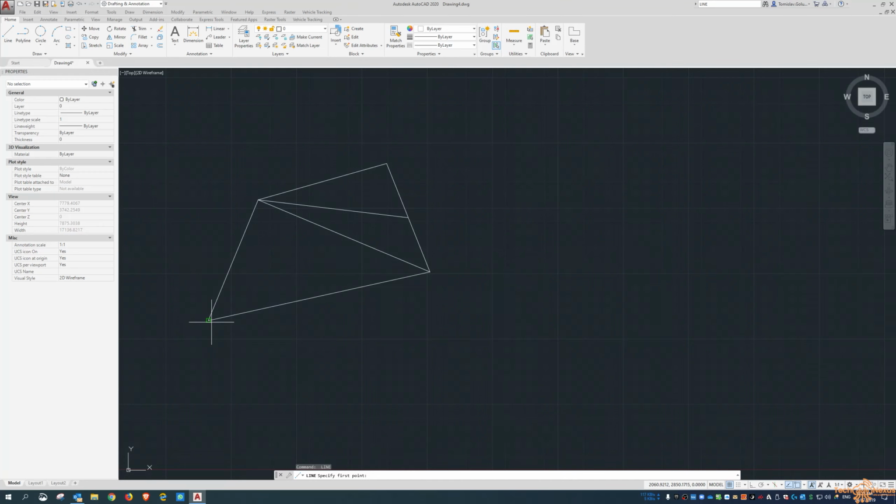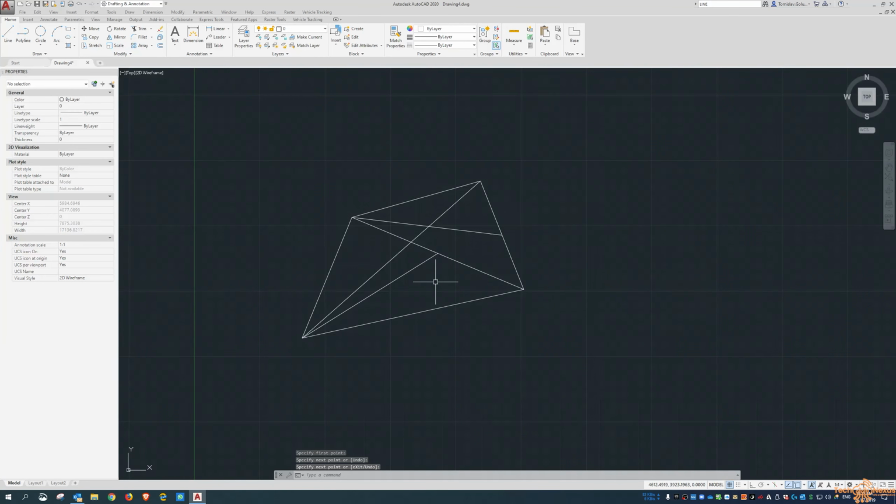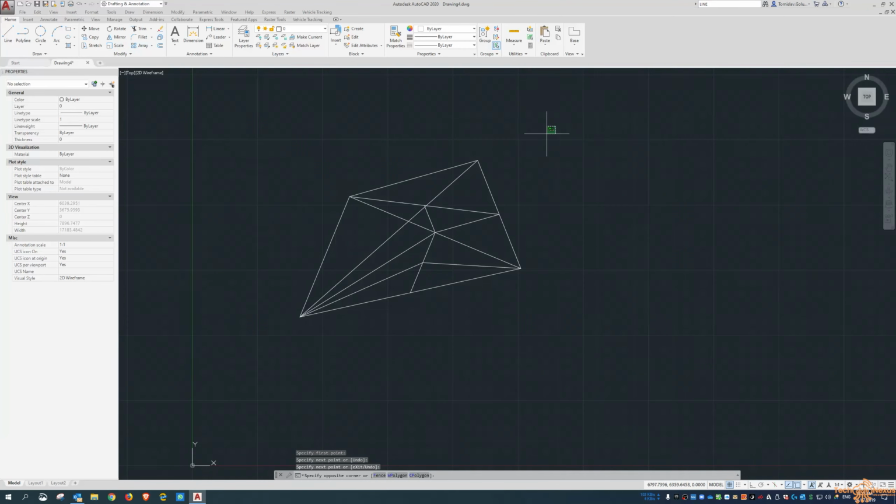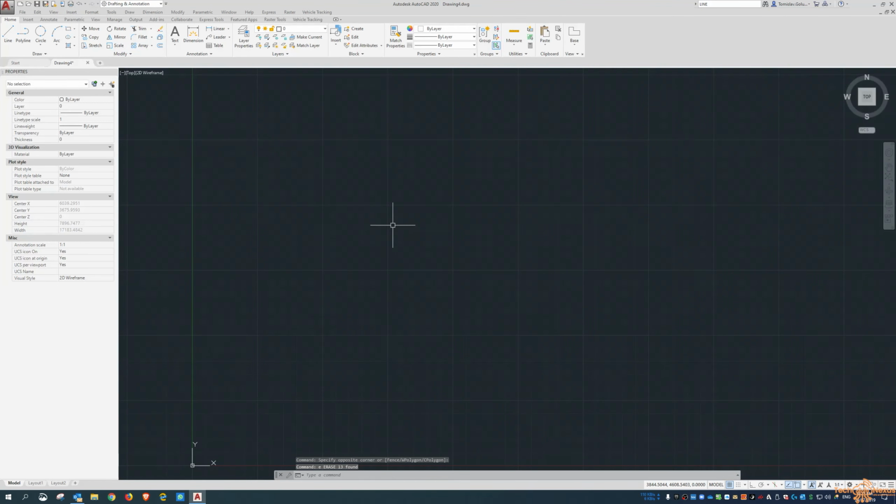So now I can just draw lines to have running snaps on. So I don't need to keep pressing shift and right click to keep these snaps going. So you can see I can just keep snapping endpoint to midpoint. So midpoint to endpoint, midpoint to midpoint. So I can go do whatever I need to do. It will come down to personal preference there as well.